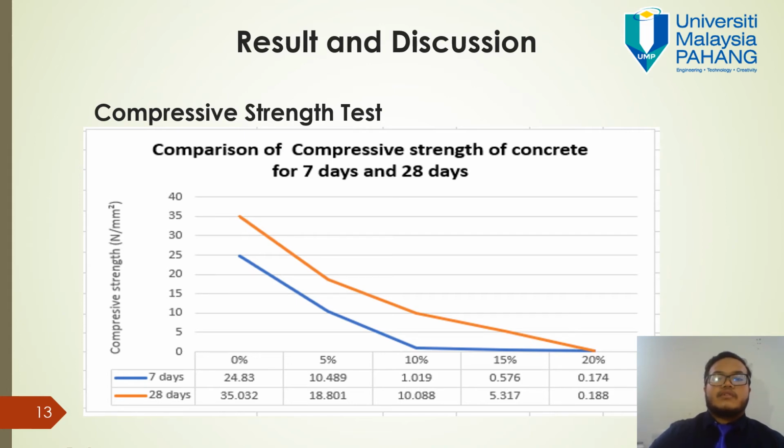According to the above result, mostly the compressive strength of the concrete cube dropped when the partial replacement of cement with Kenaf core was added. The compressive strength could be affected by the porosity and density of the concrete cube. The sample with higher porosity and lower density could make the strength lower.